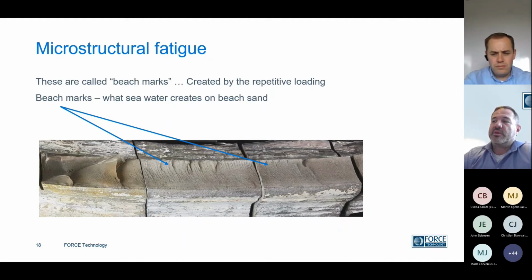The other thing you can try is to use acoustic emissions to listen, because when the crack starts, it releases energy and makes some noise. Or you could try running a voltage through it, and when the crack starts, there'll be a voltage drop. But these things are a little bit difficult to do.